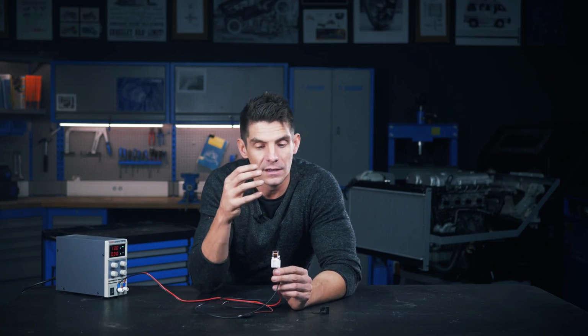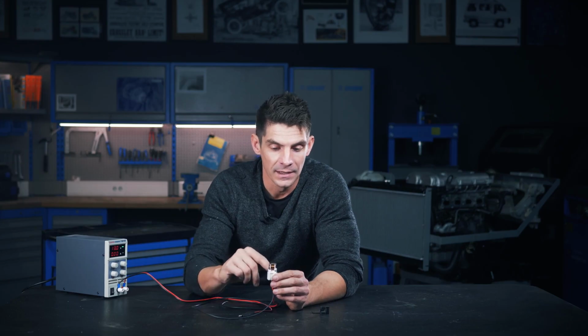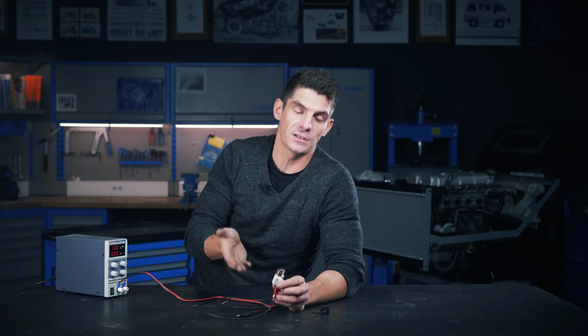So any relay which is connected or controlled electronically will include some way of suppressing a voltage spike. In our case, that's why we've got this resistor in there. You might find them made from diodes as well. And whatever this voltage suppression is, it's going to stop this voltage spike from happening. Now, for relays which are controlled by a switch, there's no need to suppress the spike because the switches don't care about that fraction of a millisecond or a nanosecond or a microsecond or some small part of a second.